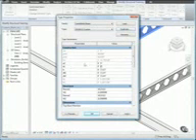For E2 or space between voids, type 5.5 inches. For B or length of sloped portion, type 4 inches. For DT1 or T depth for top beam, type 3 inches. For DT2 or T depth bottom beam, type 3 inches. Then click OK.